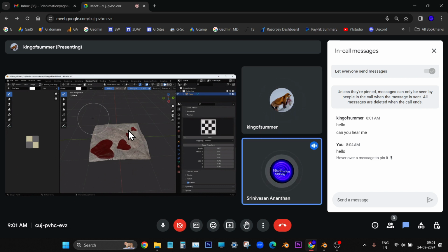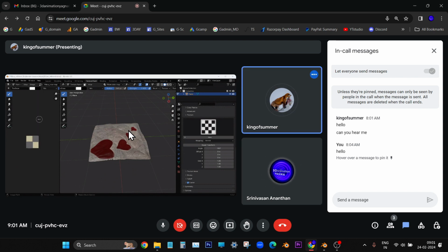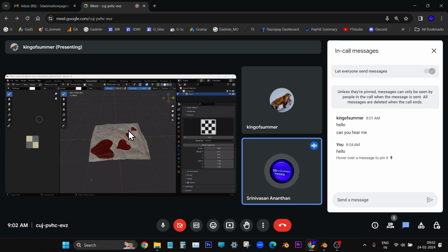No, not image save. Go to image editor, that is image editor panel, left side panel. There, image, save as. You saved it. Did you save it? If you have saved it, okay. You have to save it as color map, pillow color map dot png, 16-bit, compression 0. Once you have saved it, just tell me.